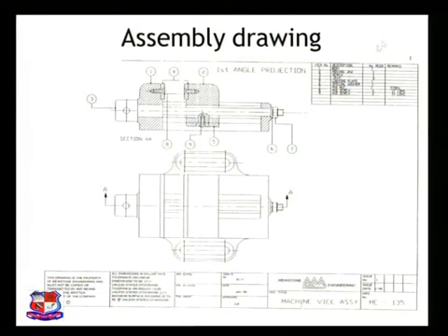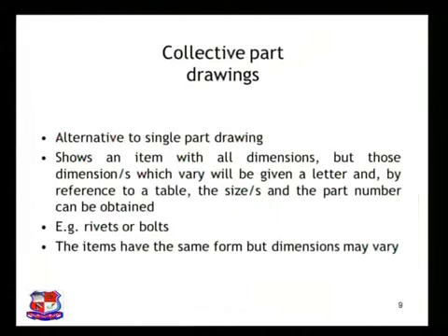And this is the part list, or it is also called the bill of material. And this is the older drawing, hence this part list is written from here 1 2 3 onwards, but in the latest drawings and in some revised drawings this part list is drawn over here. That we also will see in the subsequent slides, that this part list is prepared in the reverse manner. Serial numbers 1 2 3 4 onwards are written in reverse order.